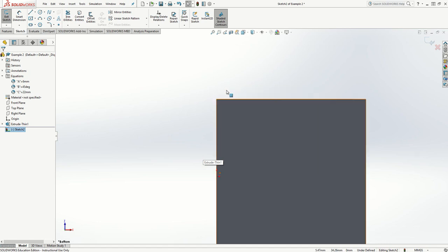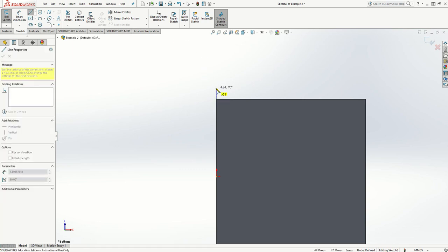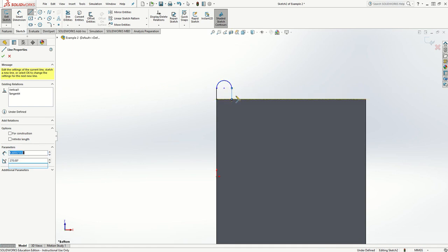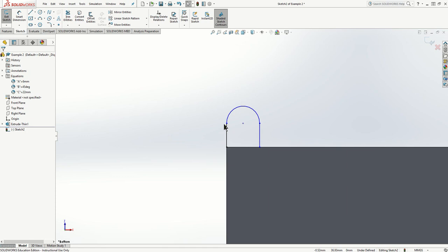Now I'm going to draw one of the arcs at the bottom. We're going to draw a line here, and we notice that it starts exactly at the bottom, so we can start from this point here. We could go up how many units, guys? For now, we don't need to type in the units. Then if I want to draw an arc, I press A, and I have an arc going. Then I go back to a line over here. So as you see, I drew a line, pressed A on the keyboard, which activated the arc command, and then I connected the line.